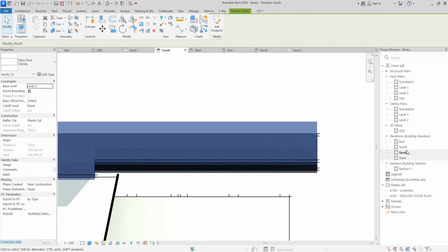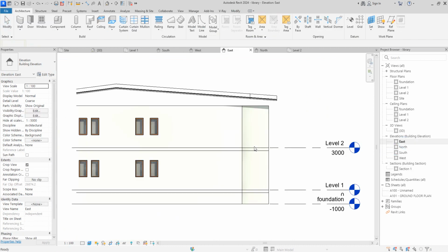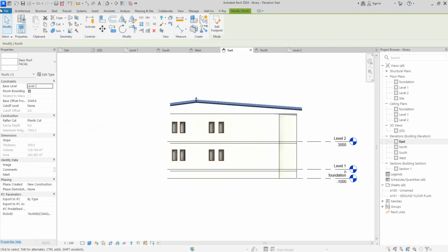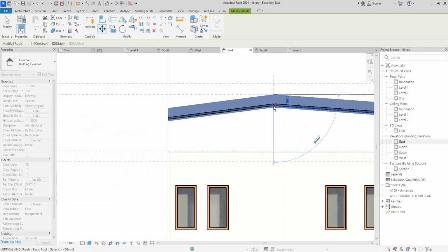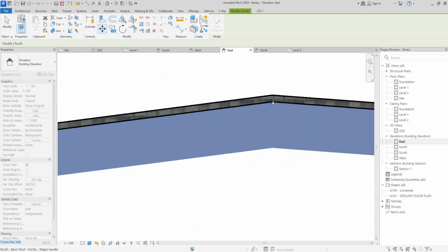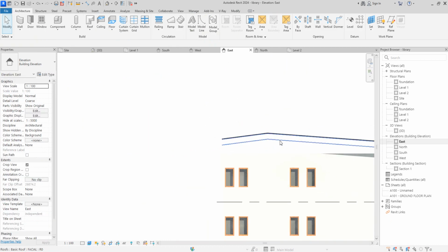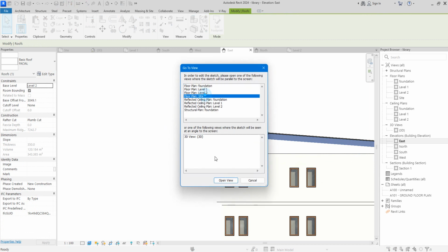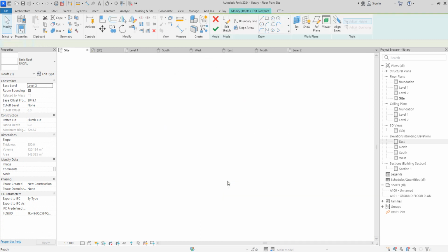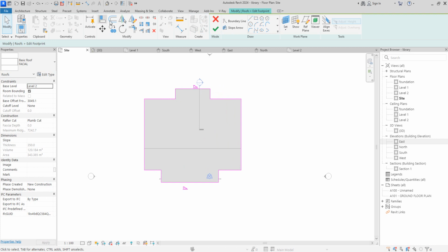What you need to do is go back to the side elevation, which is the east. From here you pick this and drop it below. Let it drop down. Good, it's set. Go back here and choose edit by footprints. Go to sides and edit it. Offset everything by just 75, offset without copy.